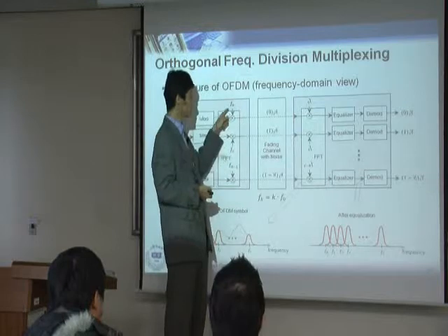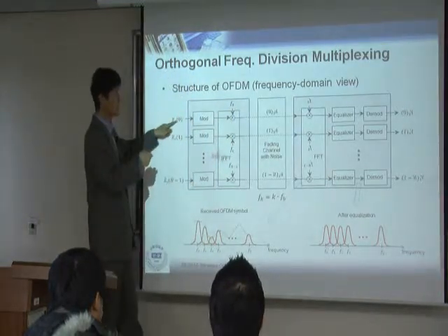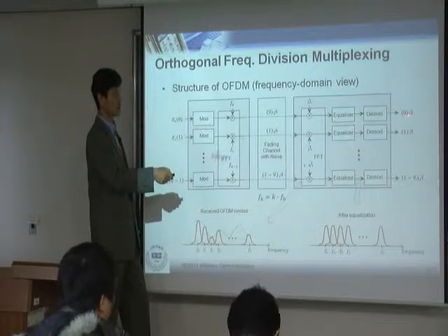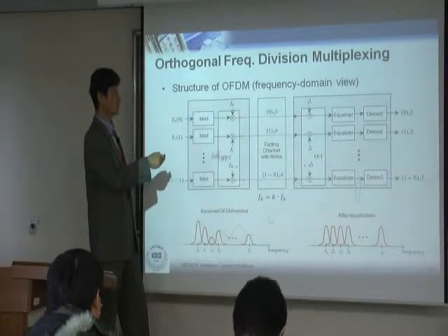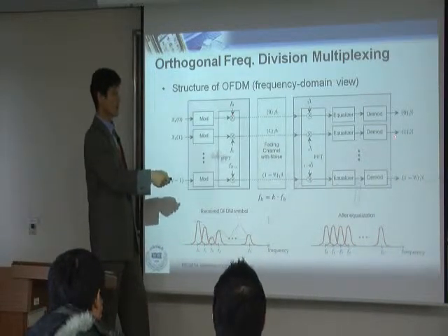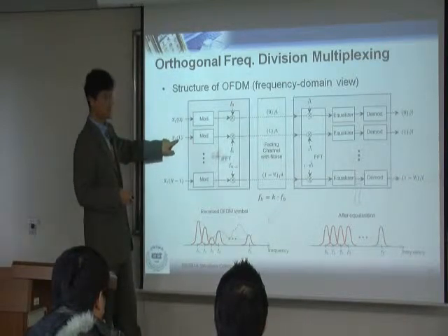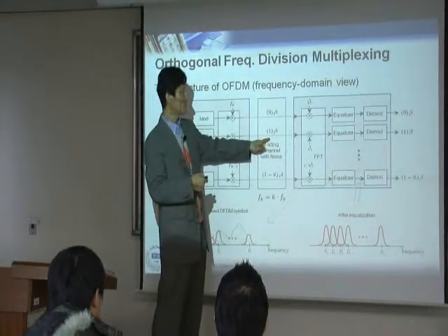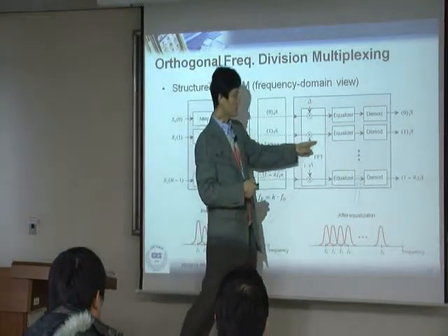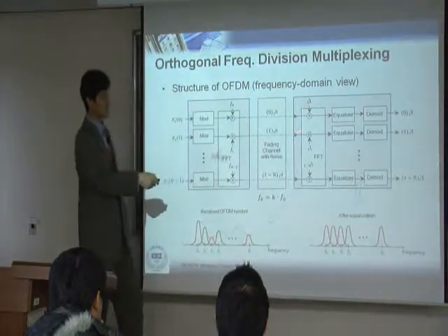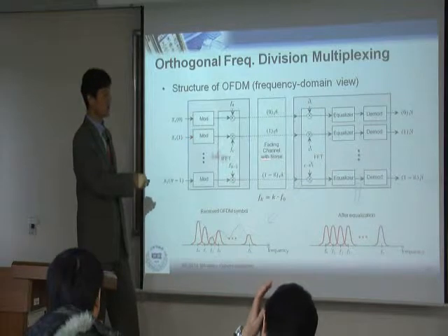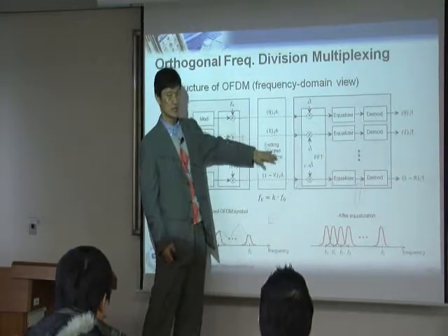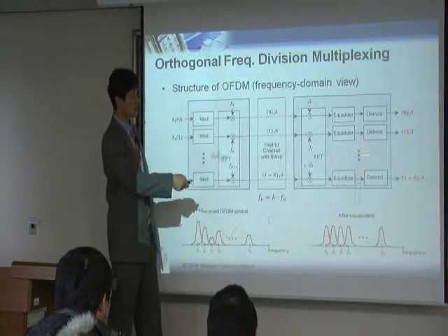It is actually the same as saying that the first sample goes through this H10 channel, and that is received by this one. So this first path, which uses the frequency F0, is completely independent. The second path uses the second symbol, which is modulated by F1, and goes through another channel called H11, then is demodulated and equalized like this. So this picture shows you that each of these frequency paths is completely independent. In other words, we are talking about multiple single carrier systems in parallel, completely independent.